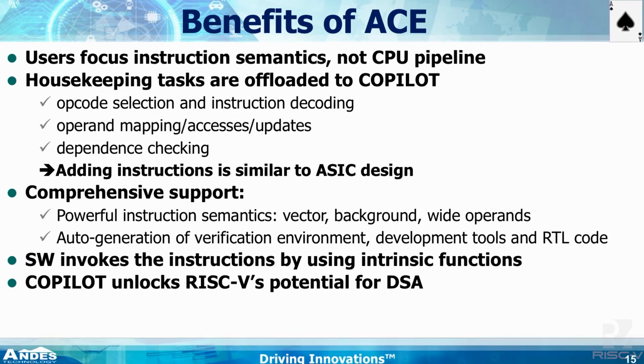So in conclusion, the benefit is, with this tool, we allow users to focus on the instruction semantics, not the CPU pipeline. You don't see the CPU pipeline at all. We hide it under our high-level interfaces. And all the housekeeping tasks are offloaded to the tool, including opcode selection and opcode optimization. We'll find the best place to put in a code.